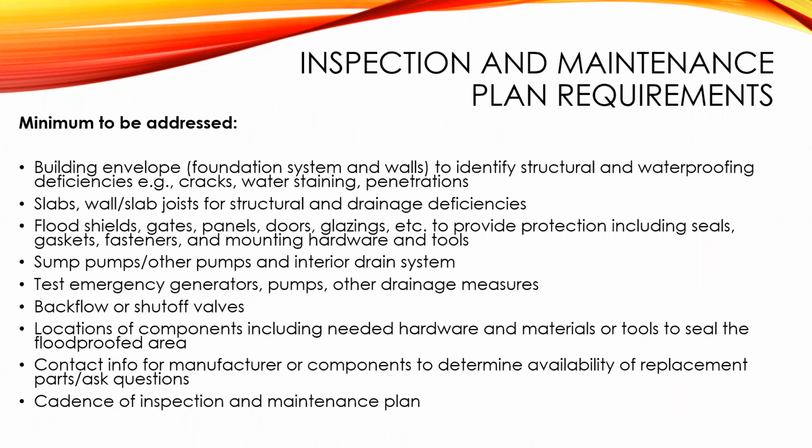And then inspection and maintenance plan requirements. So making sure that everything is the way that it was, the foundation system is still intact the way that it was. There are no cracks or other areas of penetration that have not been identified before now. All of the materials, the panels, the doors, the gates, the shields, all of that, we need to make sure that that's in working order. You don't want to find out that some of that is broken or missing during a flood event. Make sure the sump pumps are working, test the generators and all of that. And then having some kind of schedule where you're going to go back and do the maintenance and inspection again.